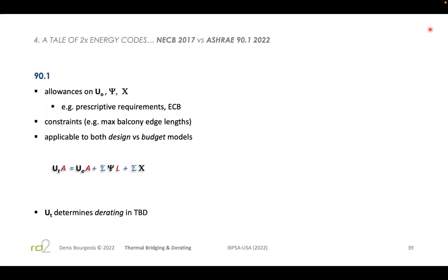And what TBD would offer in that case is, okay, based on all of those and based on the linear link scenarios in your building energy model, here's the UT on a surface per surface basis. So TBD won't be satisfied modifying your overall building construction characteristics. It will make clone copies for each and every single surface in your model and make sure that the derating, which simply means you're taking all those extra conductances and modifying the insulating layer thickness to accommodate the effects of thermal bridging. So TBD will do this automatically.